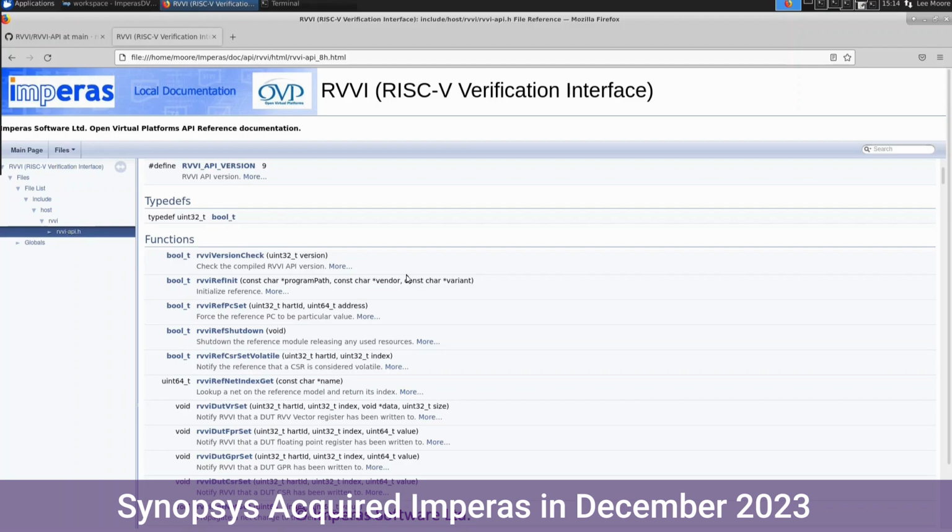So you can say, does it handle misaligned loads or stores? Which of the extension libraries are supported? So the model downstream that we use as part of the verification is highly configurable, not only from the standard set of specifications within the RISC-V organization's definition, but also for the custom extensions, be they CSRs or instructions. They can also be described as part of this environment and used as part of the entire verification flow.